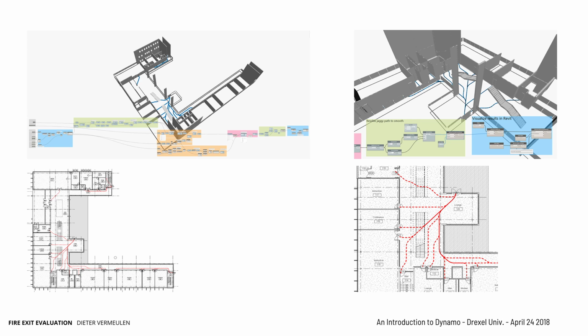And again, those are calculations which you could do manually, and it takes some time, and then every time the design changes, you redo the calculations, you redo it, you redo it. But it really makes more sense to capture that intelligence into a computational format, in this case a graph. And that's exactly what he's done. So this is what the script looks like, and the nice thing about Dynamo is that you can also get an in-screen preview of the geometry. You don't have to always be working in the Revit environment. You can preview it directly in Dynamo as well.